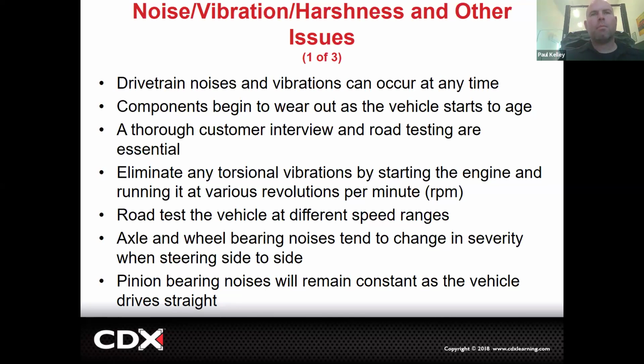Similarly, once the bearings are damaged, then we really need to fix the bearings. However, if you fix the bearings and you don't address the leaks, you're probably going to end up with repeat failures, right? So it's kind of interesting. We do the MPI. If you do the MPI well and you actually check the fluid and you top it off if it's low, you probably won't. The customer shouldn't really have any of these bearing failures. So we're self-justifying by preventative maintenance.